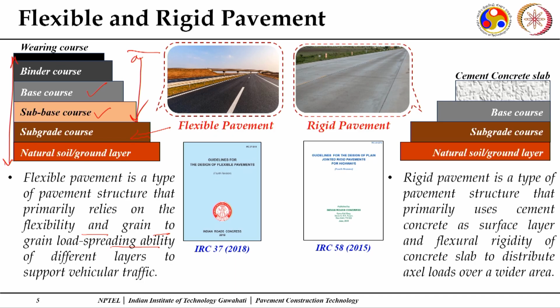Now, for this particular one, the Indian Roads Congress has given guidelines, IRC 37. IRC 37 helps you to work out the crust composition of a flexible pavement and see whether this is good enough for a given design traffic or a good amount for the existing traffic loading situations.